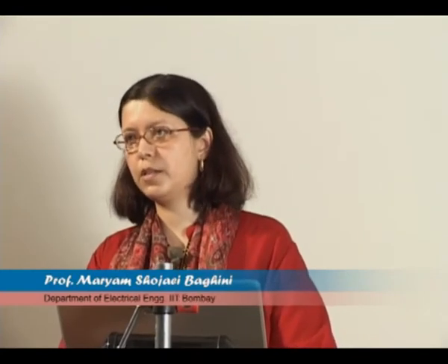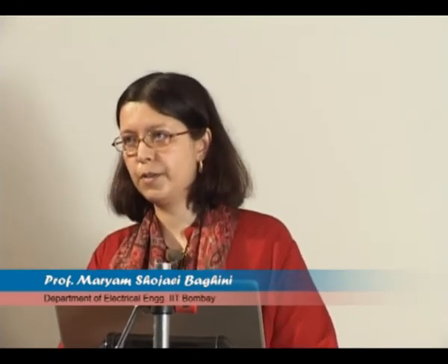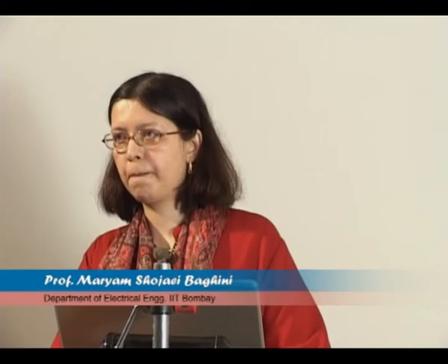Whether you need more or less, 1.25 is something which we naturally get from silicon. So it is preferred to start with that and generate everything out of it. Of course, now we can generate smaller values and then still generate other values that we want. Because when we want something other than 1.25, we add a circuit. That requires additional area, but that is okay.